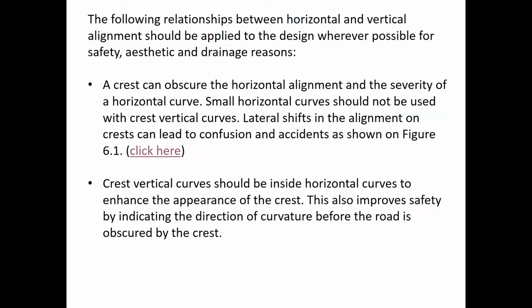If the vertical curve is within the horizontal curve, you will be able to see the horizontal alignment clearly. So when you reach the exit point, because the vertical curve is within the horizontal curve, it is not able to obstruct the horizontal curve.